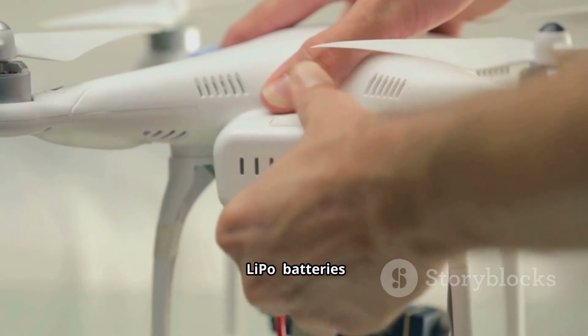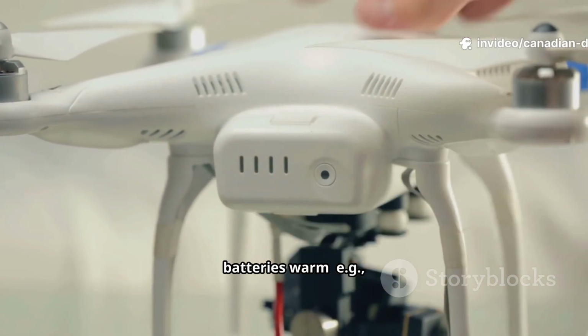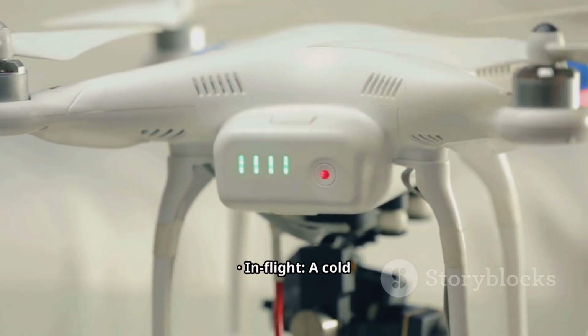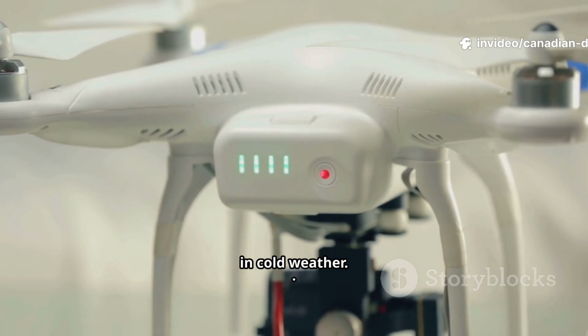B. Temperature and battery performance. Lithium polymer, LiPo, batteries hate the cold. Their ability to hold a charge plummets in low temperatures. Pre-flight, keep batteries warm, for example in an inside pocket, until you are ready to fly. In flight, a cold battery will show a sudden voltage drop, leading to an unexpected low power warning and forced landing. Always account for reduced flight time in cold weather.